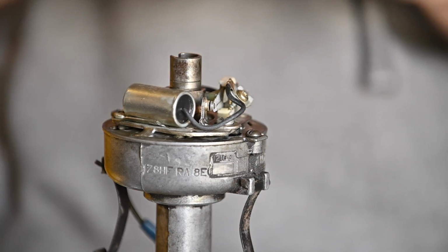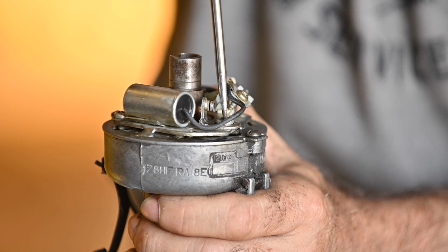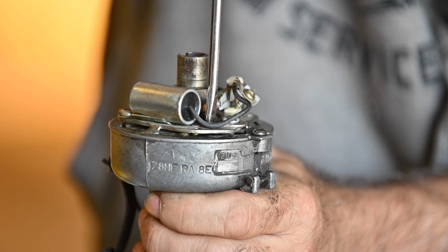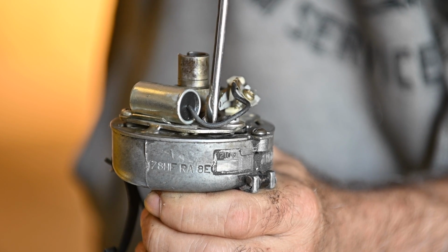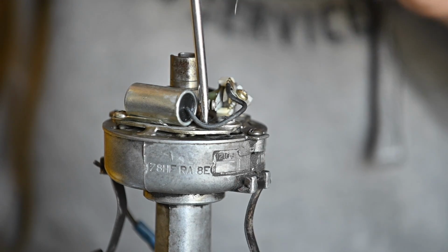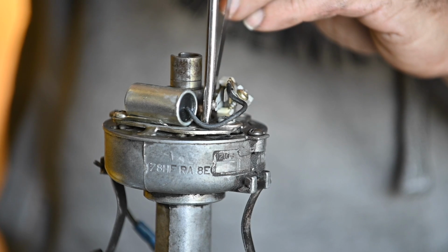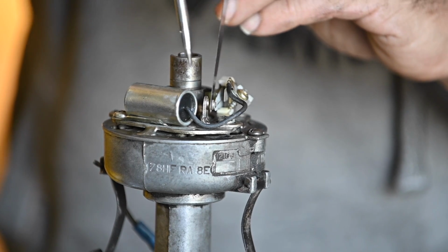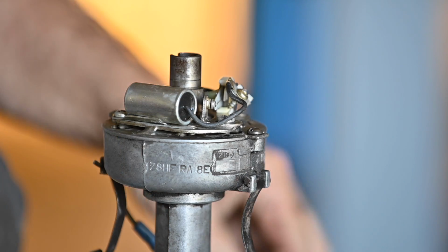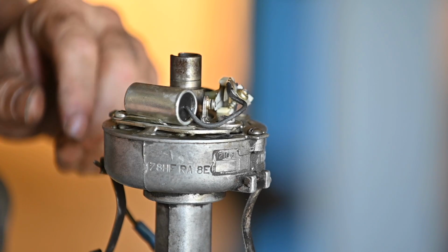And I'm gonna just try that, and hopefully you can see it. And let me just open that up here for a second. And then you can actually put the screwdriver in and move these points around, as you see. So that's what you can do. So that's how you adjust the gap. So you adjust the gap, stick it in there, and then just move the points until you have a good fit. And that's all there is to it, to adjust the breaker points. And once you've done this, then you can double check it on the car itself and measure the dwell angle.